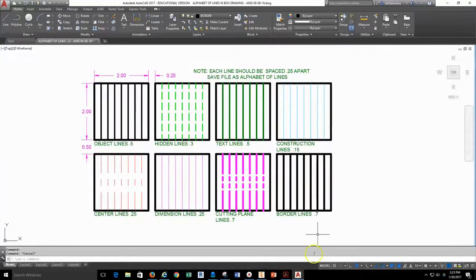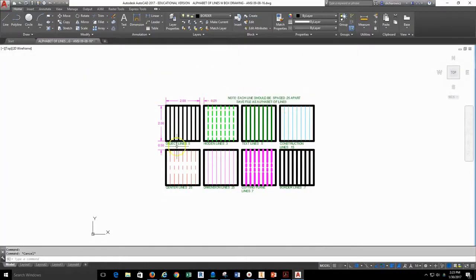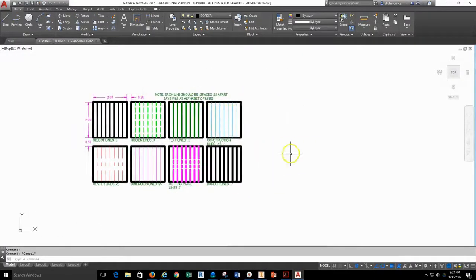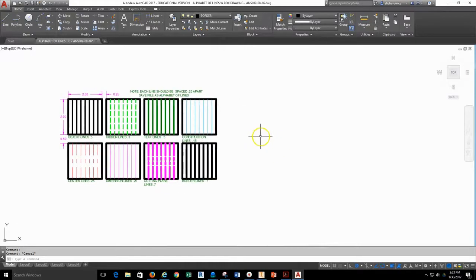Now, if we go into AutoCAD, you can see that this is what the completed assignment would look like in your model space, and I can run through a very quick approach to creating some of these boxes using the Move and Copy tools. First, I'm going to select the Object Viz line, because that is the layer that the boxes should be drawn on.